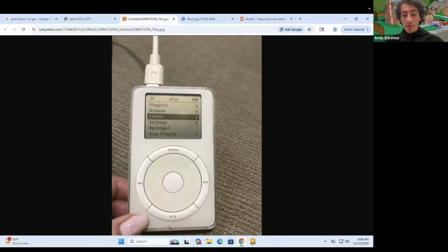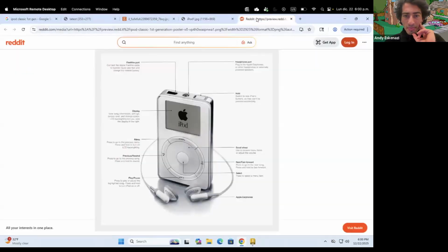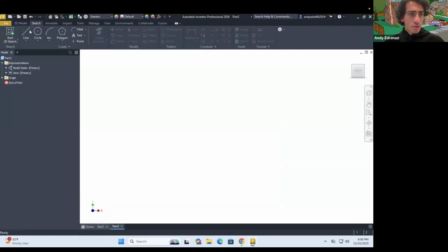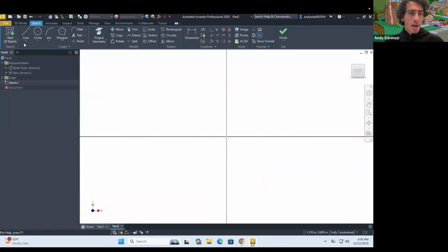So we're gonna make all of these through a sketch. And then we look at the side, but essentially we're gonna eyeball most of these dimensions. So nothing too fancy. I think this is probably the nicest picture that we're gonna use for all of this stuff right here. So let's go here to our friend Inventor. Let's go to Sketch, Start. I'm gonna choose the XY plane.